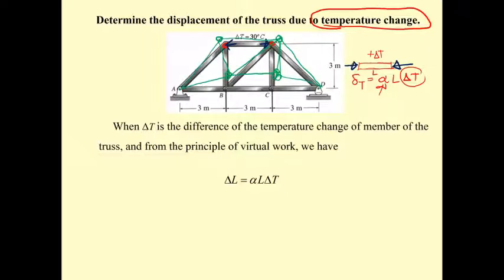Okay, most of the time when the roof heats up, the member on the top chord is going to expand, and then it's going to lift the truss up. That's good because it's going to resist the deformation of the truss due to the dead load or even the live load. Now, if you would like to determine the deflection at some point of the truss due to this, let's say if you're interested in it.